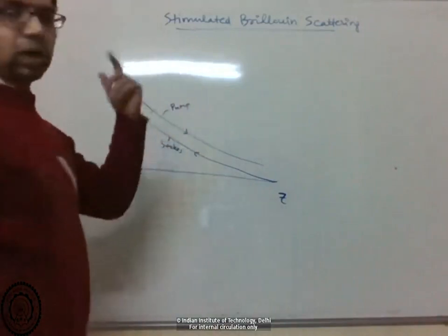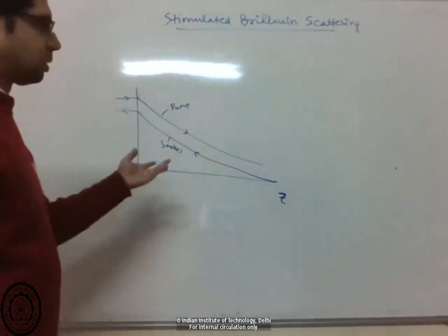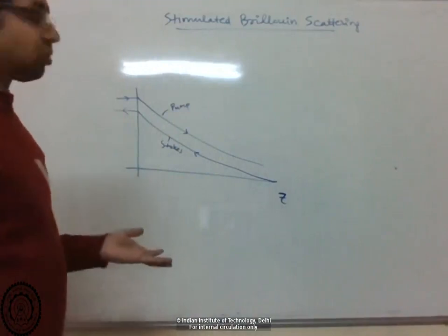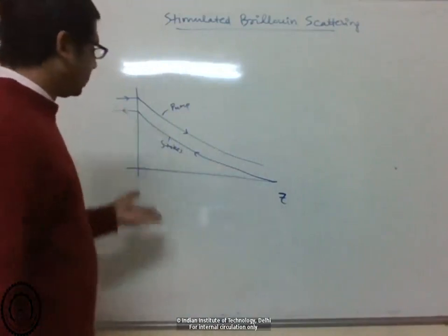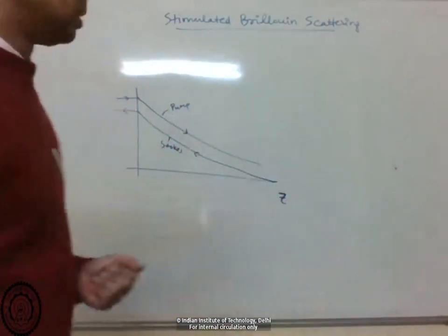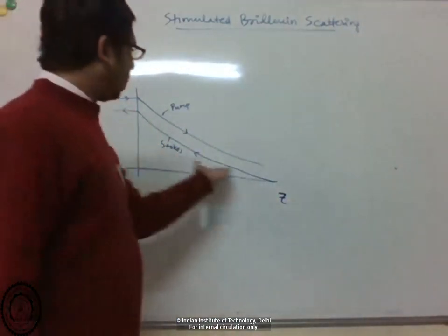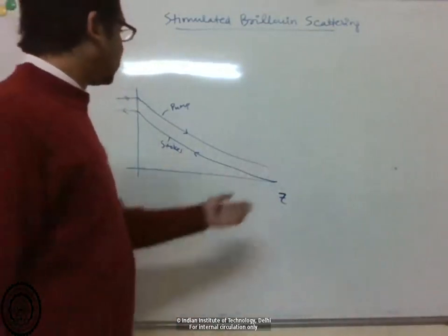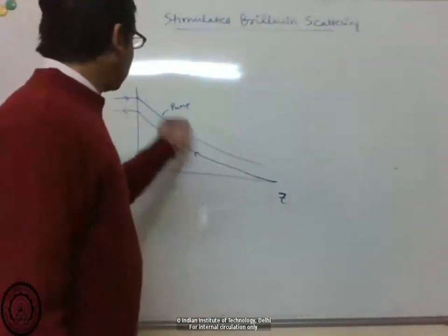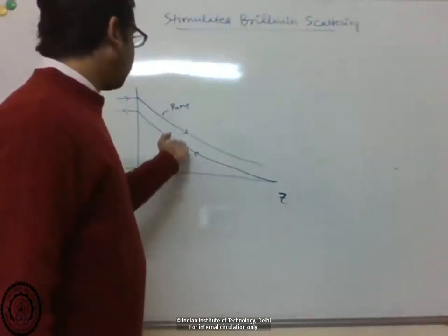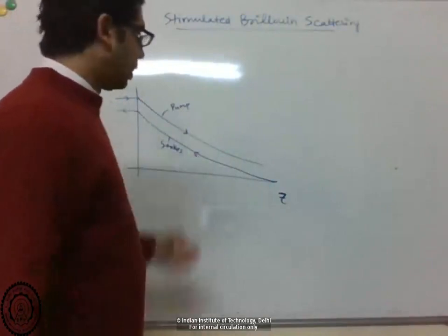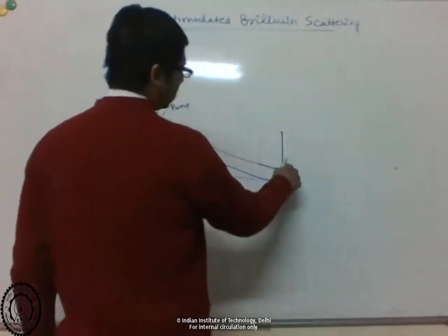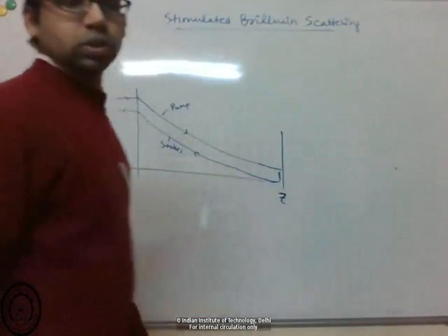So we saw that for 10-20 milliwatts of pump power and a propagation distance of a kilometer or so, in a typical optical fiber, the gain that the Stokes experiences could be like 100 billion. So you don't need any Stokes input from the other side. Any small fluctuation or noise gets amplified so much that most of your pump input signal can be converted to the Stokes. So that at your receiver end, you receive very little or no signal.